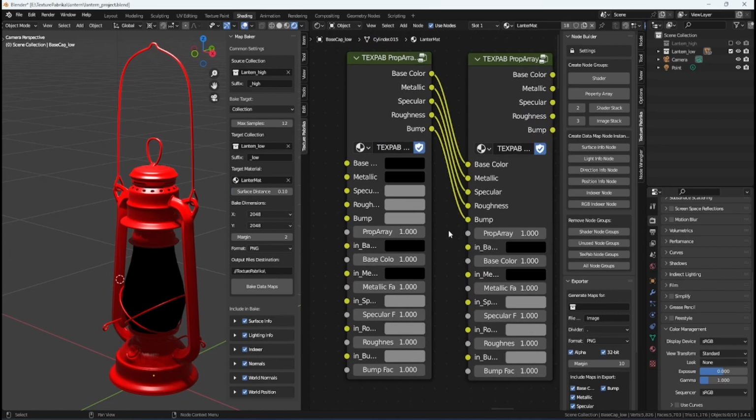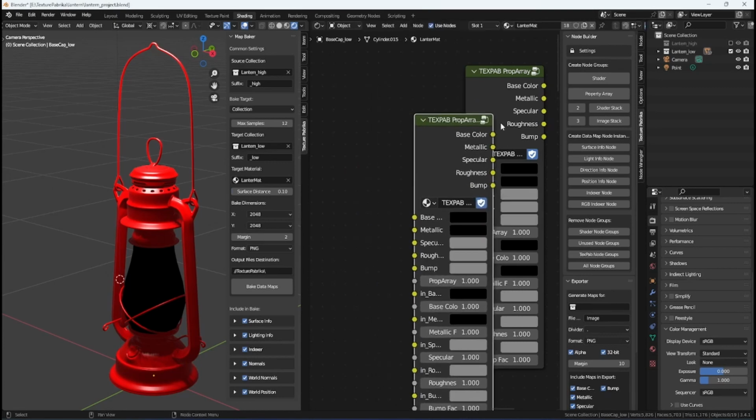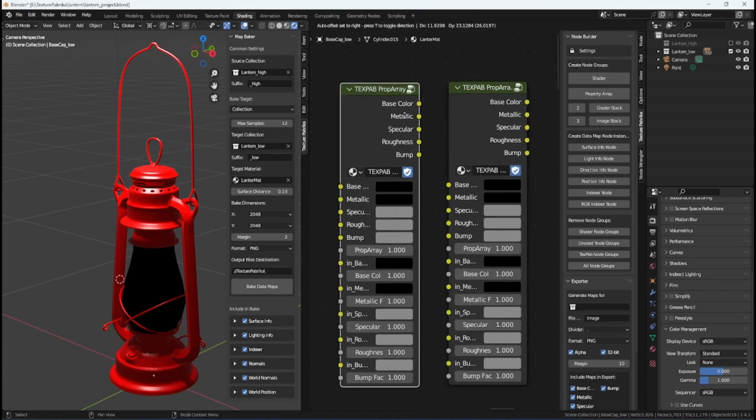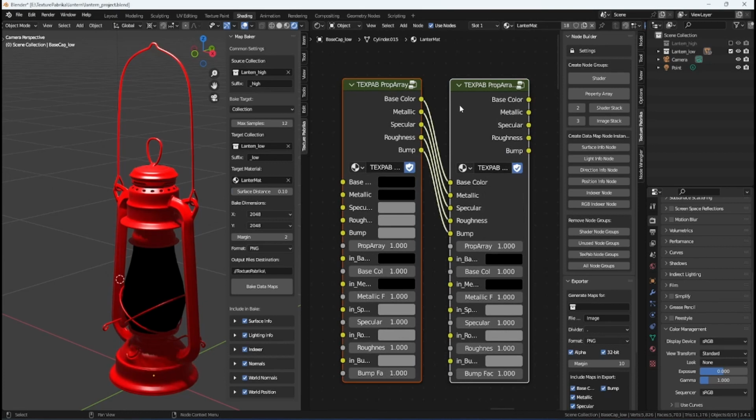This allows us to create a node structure that we can easily arrange and rearrange. So let me just quickly show you how that's done. On our keyboard, hold the control key and right click on our mouse and drag a line over all of these lines over here. And then we can just quickly swap places for this too, and press the F key as many times as there are properties to connect.